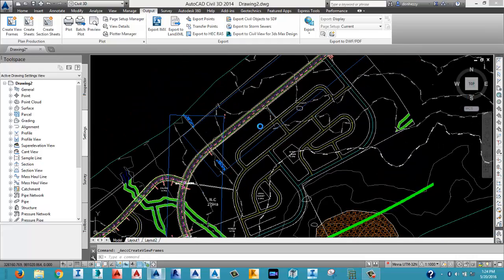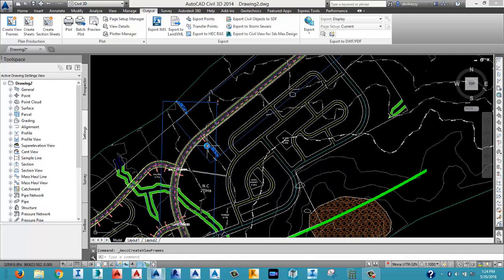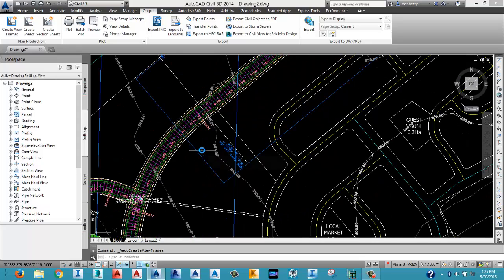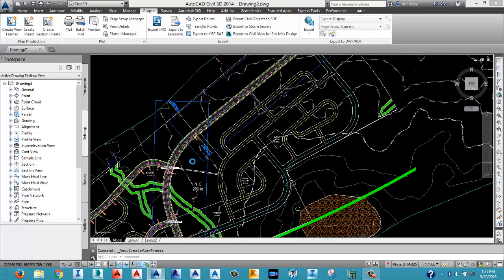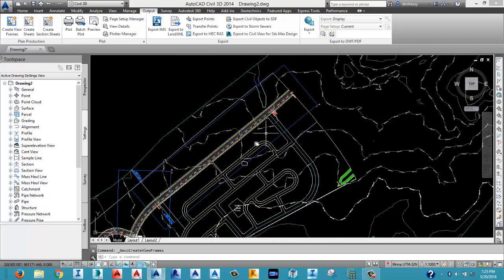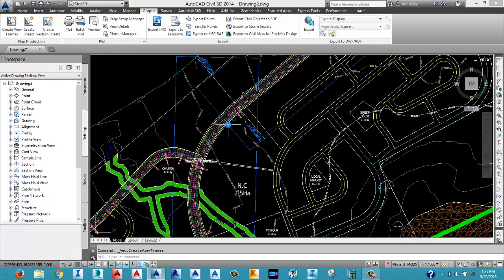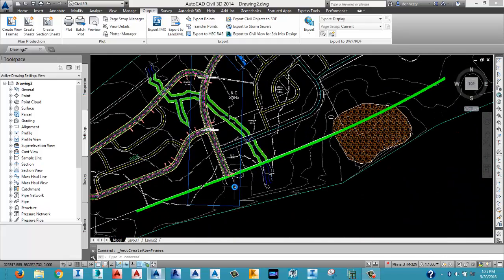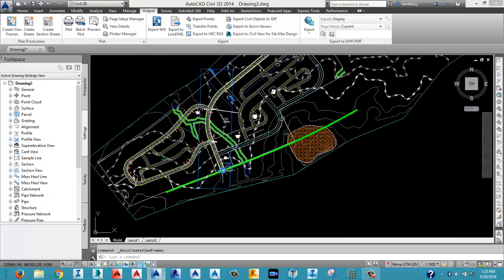This blue line, sorry, the blue lines are your view frames. So you can see the point where the blue lines terminate. That's just the view you'll be seeing on individual sheets of paper. So the first view frame is giving us from chainage 0 to about 700 something meters. So that's what will be displayed on the first paper. Then the second paper we capture the remaining length of the road. So you're having two papers to represent your design.